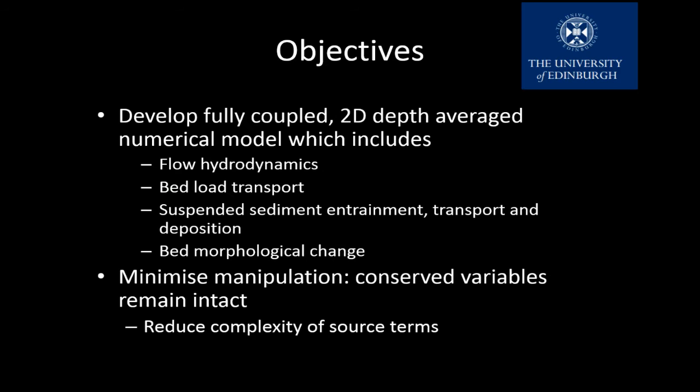So one of the things I wanted to do with my PhD was to see if it's possible to develop a model that is fully coupled, so at each time step the hydrodynamics of the flow is updated, and at the same time the sediment concentrations and the changes in the bed are updated. And I wanted to include bedload transport and suspended sediment transport and see what happens if we can have the two of them together.